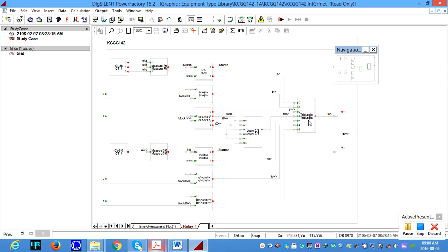So you apply these signals to the trip logic. You see stage 1 is coming, this signal 0 1 0, and stage 2 is coming to 1, and then whatever is coming, it is going to issue the trip signal. If you want to apply the ground fault, we didn't do that, but we can apply it as well, and the same applies for stage 1 and stage 2. Stage 3 will not be considered for the ground fault in this case, because we have not applied stage 3 as well. This is just a quick overview of this relay wiring diagram